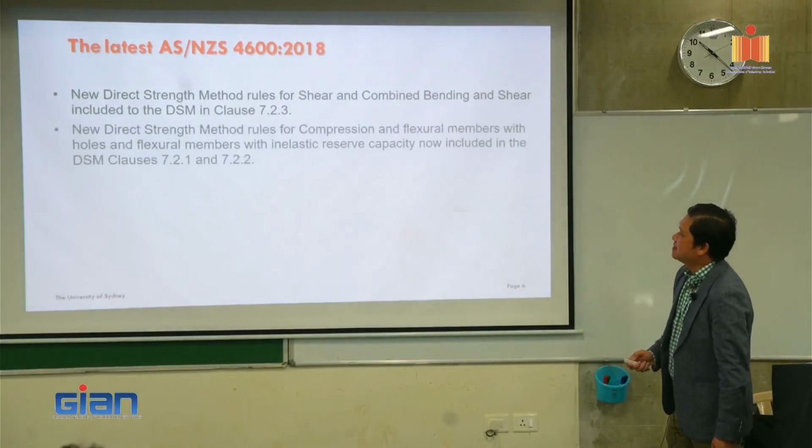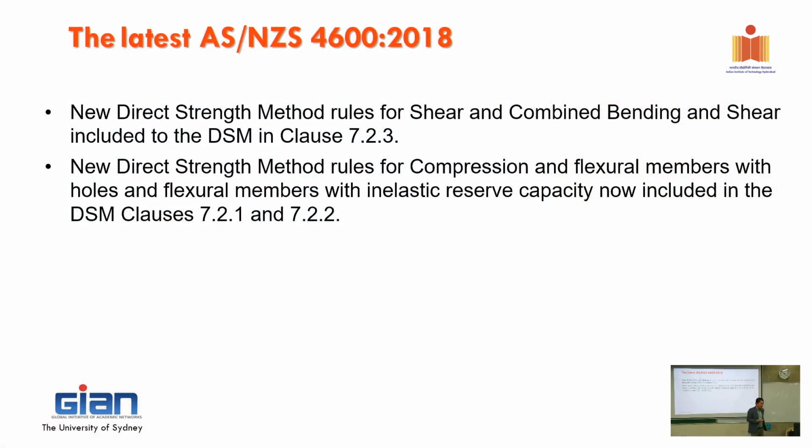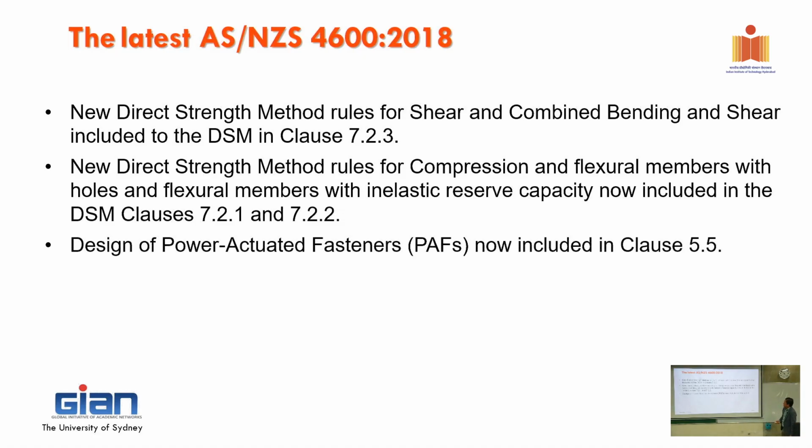Okay, and then we introduce new direct strength rules for inelastic reserve capacity. It's based on work from Professor Ben Schafer and his PhD student at Johns Hopkins. So that was included into that standard, and then now another interesting rule is for the design of a new type of connector.